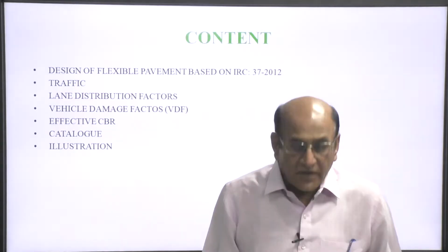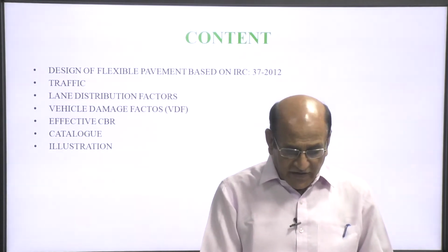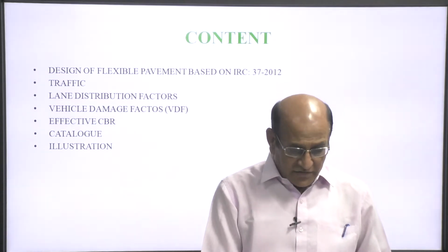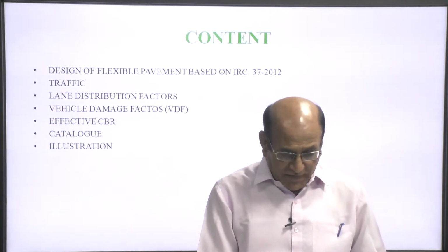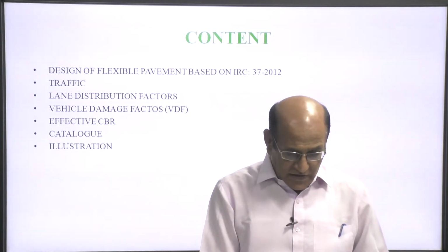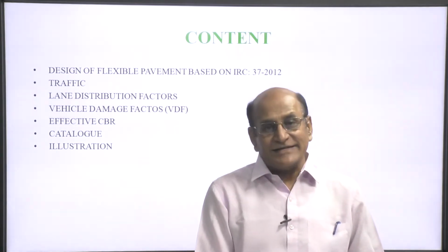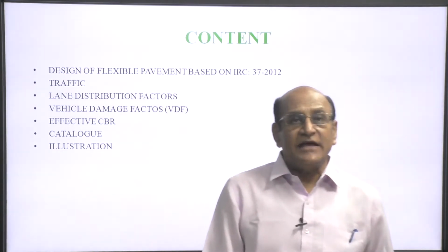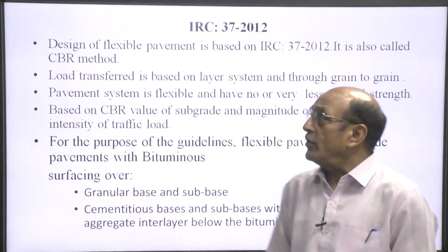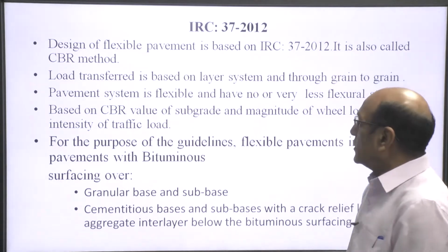S.K. Duggal. The content of today's topic is design of flexible pavement based on IRC 37 2012, traffic, lane distribution factors, vehicle damage factors, effective CBR, catalogues and illustrations. So, we will discuss here one by one. The design of flexible pavement is based on IRC 37 2012. It is also called CBR method.